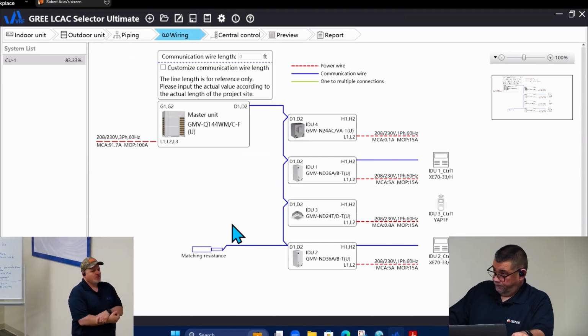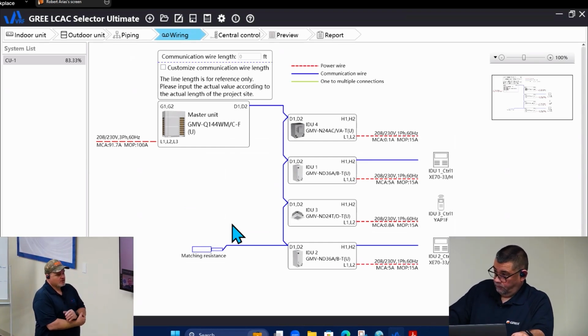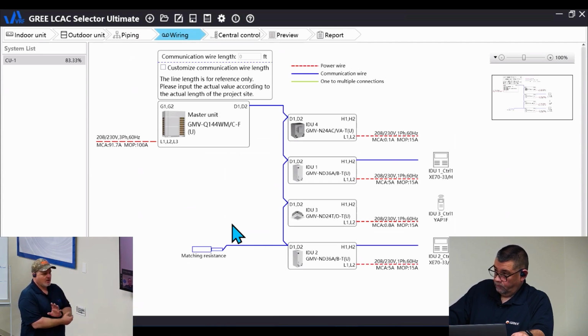So when you make your connections, when I say grounded shielded, there's a good example of that drawing in the quick start guide for our single phase. They're wired exactly the same, okay? But I highly recommend you ground it on the outside, and then you're going to go D1 and D2. You're going to land those on the screws at D1 and D2 on the indoor unit.